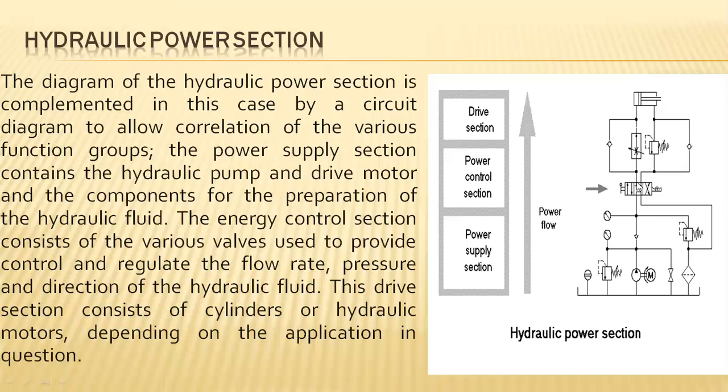Initially, it is in the null position, with no connections. At that position, the fluid pumped by the motor drains back to the oil reservoir, and no other connections are made here.